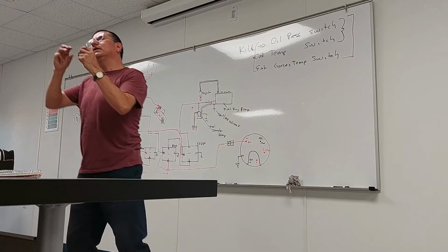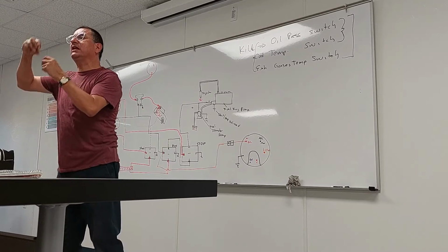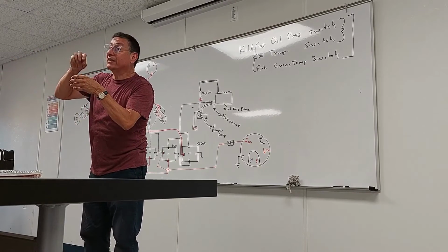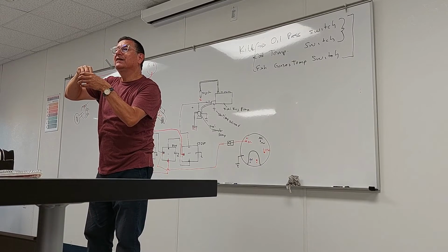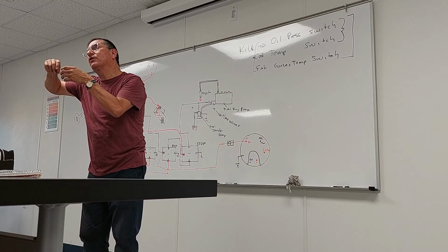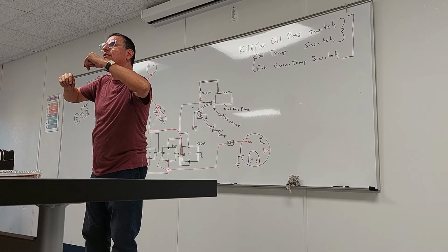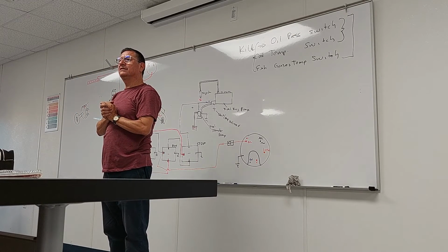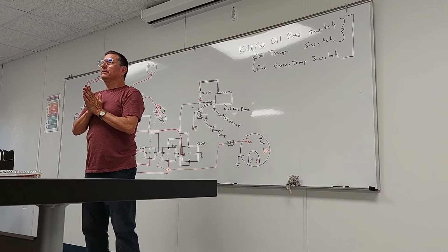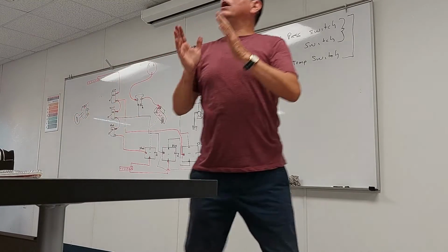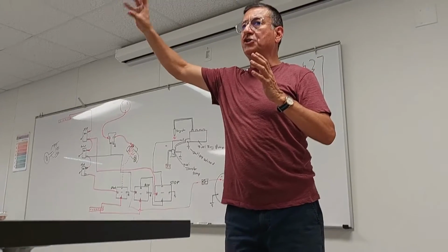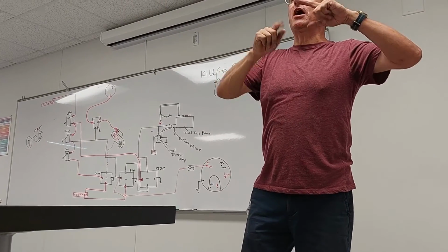Where are the coolant temperature sensor and the coolant temperature switch located? In the thermostat housing, where the thermostat is located. At that point you have one hole for the sensor and another hole for the switch. Nice, huh? It's clear, my friends? You always have a sensor and a switch. The sensor is for the computer to engage, and the switch is to interrupt.